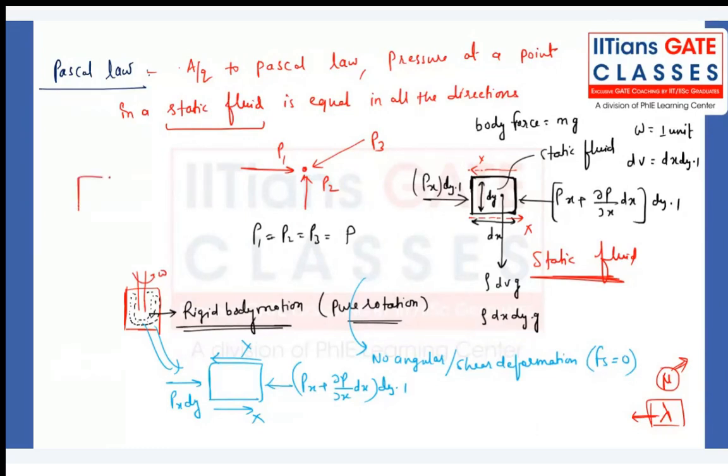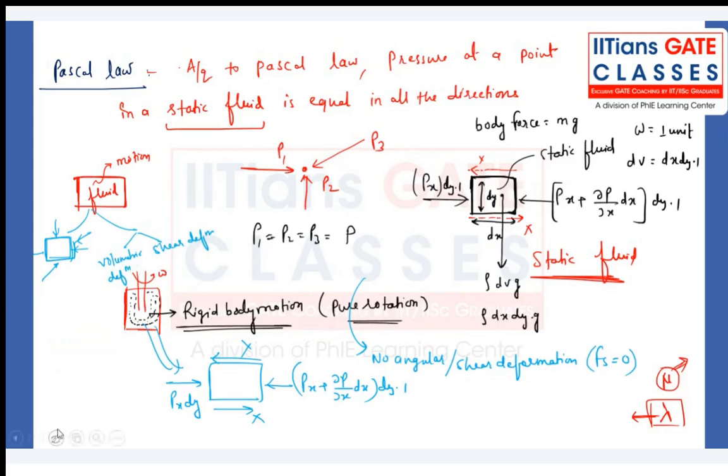So remember, you take any fluid element and apply some motion to it. We categorize into two things. One, we treat it as a hydrostatic state of stress where it is subjected to an equal amount of pressure in all directions. Second, we say it is undergoing volumetric deformations and also shear deformations. And likewise we determine the Navier-Stokes equations, right?